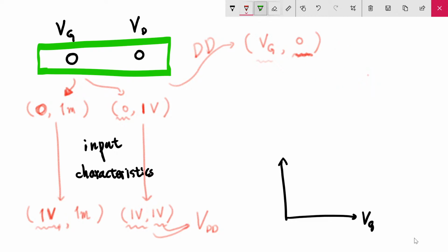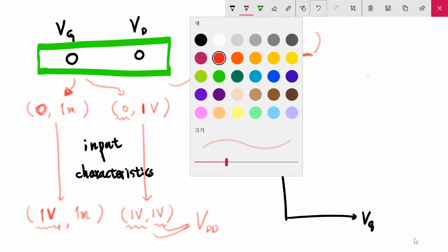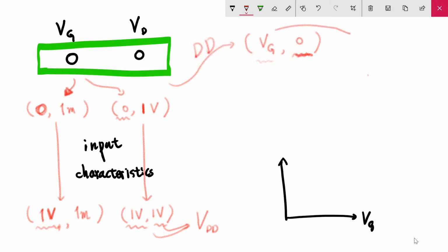Okay, great. After you arrive at that VG value, so what will be the VG value? I just recommend you to introduce like this. Of course, 0, 0.1, 0.2, 0.3. So with 0.1 volt step, please increase up to 1.0. Then you will have 11 different cases for your VG values.